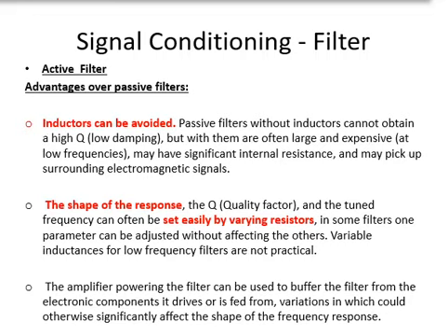Advantages over passive filters. Inductors can be avoided. Passive filters without inductors cannot obtain a high Q or low damping, but those with them are often large and expensive, may have significant internal resistance, and may pick up surrounding electromagnetic signals.